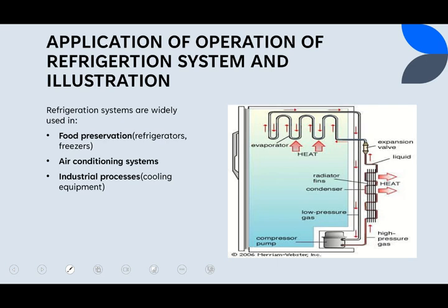The compressor draws in the low pressure refrigerant gas and compresses it into a high pressure refrigerant gas of high temperature. This refrigerant gas is then condensed into a liquid refrigerant at the condenser, where it undergoes expansion at the expansion valve for cooling to take place. The cooled refrigerant moves into the evaporator, where heat exchange occurs, hence taking out the heat from the refrigeration area, that is the low temperature space. The heat vaporizes the refrigerant, where it returns to the compressor for the cycle to continue.